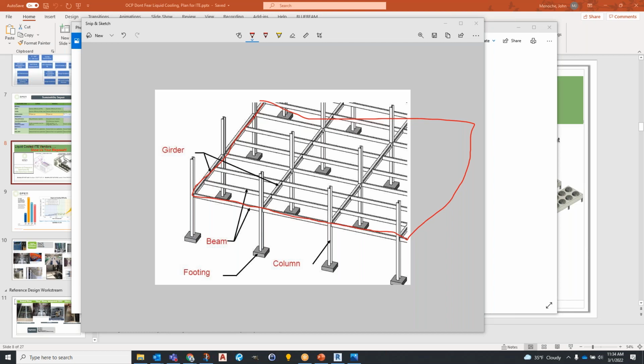And from there, the engineer needs to understand that as the IT layout is configured, and as the room and the space is laid out, how that impacts point loads, how that impacts what the actual average floor load is, that all changes, right? That number changes, but it's a starting point to say that, if you look at the physical footprint of this piece of equipment plus its clearances, this is the loading over that area. Yeah, I think it's a worthwhile exercise to get the data from the manufacturers and then walk it through.